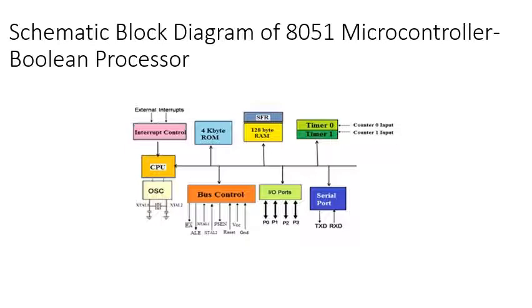The 8051 has separate address space for program memory and data memory with the help of modified hardware architecture. The program memory can be increased to 64 kilobytes. Approximately 4 kilobytes of program instructions can be stored in the internal memory of 8051. The 8051 can address up to 64 kilobytes of external data memory.